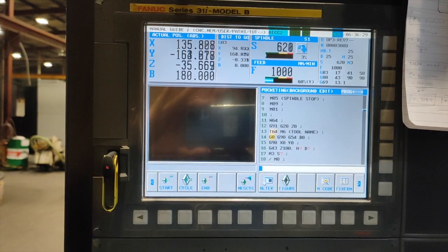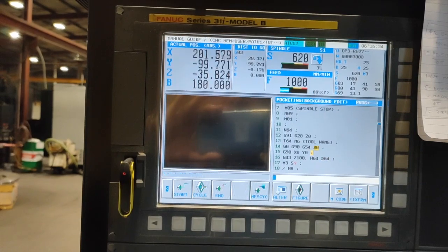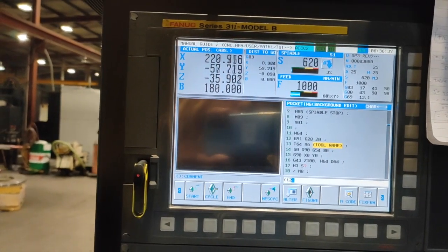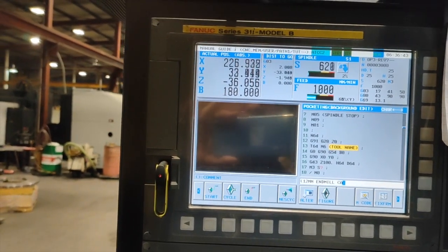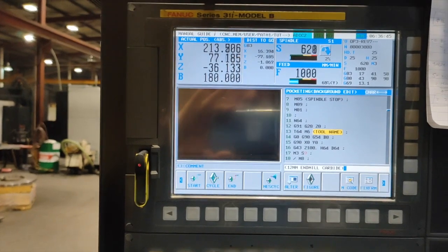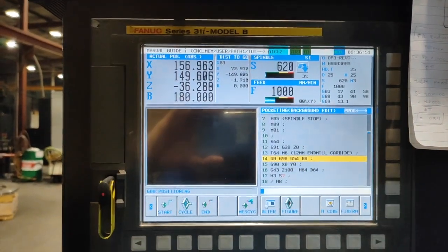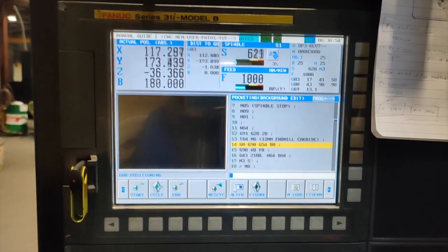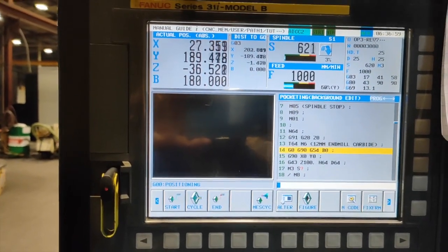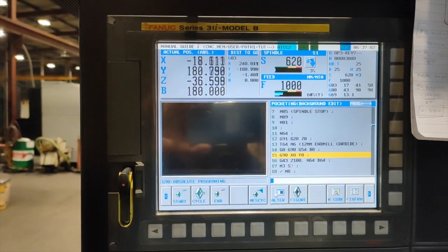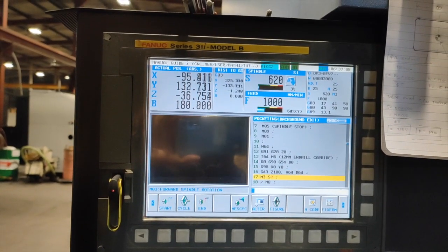Tool 64. Our H is 64. Same. D is 64. And we change the name, 12 mm end mill, say carbide. And then we have this again, our G-origin, G54. That is very important, the angle of the table, so that you know exactly which angle you are going to, and you are going to position at the middle and 100 millimeter above the job.